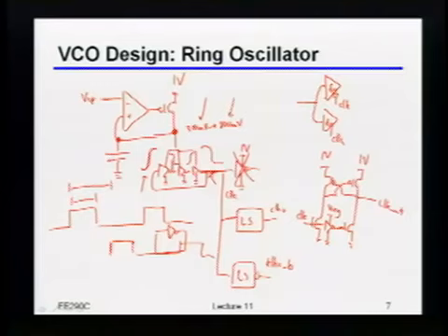And inside, if it's a 3-stage, where did you get the clock bar? Because there's no 180-degree phase. That's right. So that's what I'm saying, I won't really get clock bar. I'll get clock bar plus 60 degrees or whatever it is. Right, and then when you choose two parts, how do you get the clock and the clock bar from the beginning? Oh, okay. If I really did it, I would probably just phase split or something like that. Then that phase splitting depends on the supply voltage, right? Yeah, that's right. So by the way, there is no perfect way to do it.